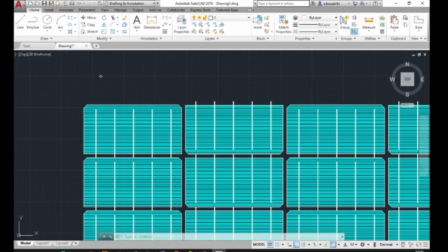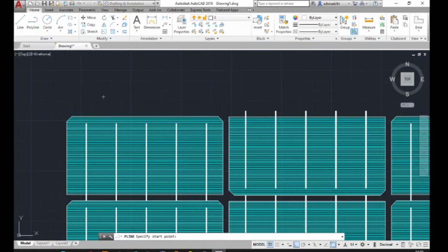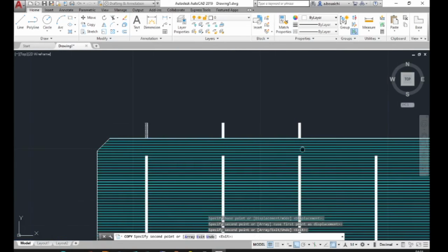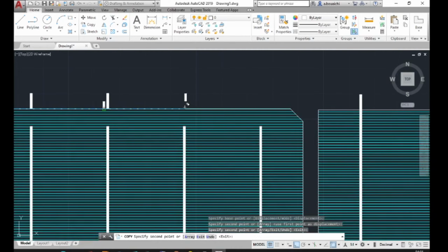We are also going to work with polyline. Press this point, take your cursor above and type 6, enter. Press the copy command, select this line, specify the base point, and specify the other places of this grid line.